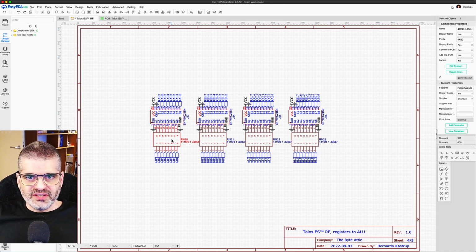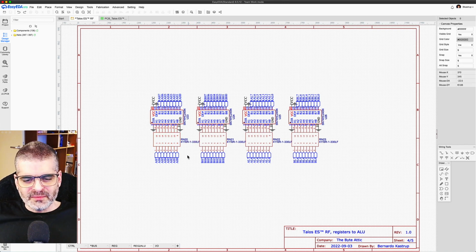So to match the impedance of the two, you add 33 ohms right next to the driver pins. So the output impedance becomes 50 ohms, which is the same as the trace, and then you don't have the reflections. You don't even create the reflections to begin with. That's a valid way of thinking about that. The other way of thinking about that is what I just mentioned earlier.